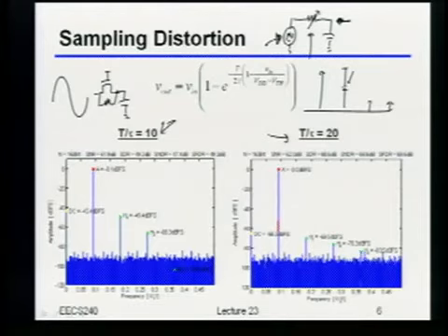Okay, so how can I make the change in the VGS smaller? Increase VDD. Ah, okay, yeah. Yeah, that's actually exactly it. Increase VDD, or equivalently, somehow make VN smaller relative to VDD, right? That's actually exactly what I wanted. Now, why do you not want to do that? Power. Okay, so if I increase VDD, I'm paying more power.